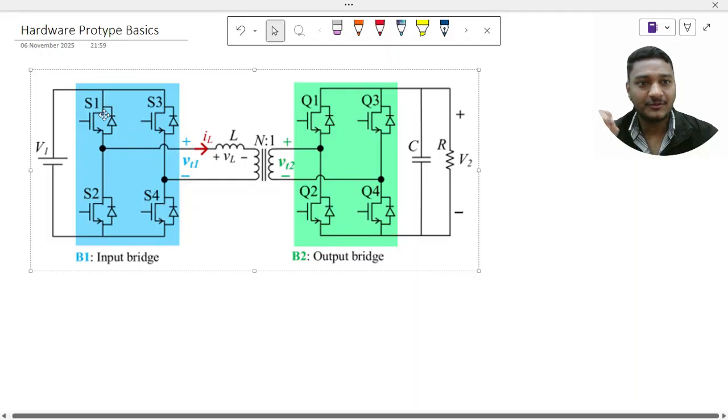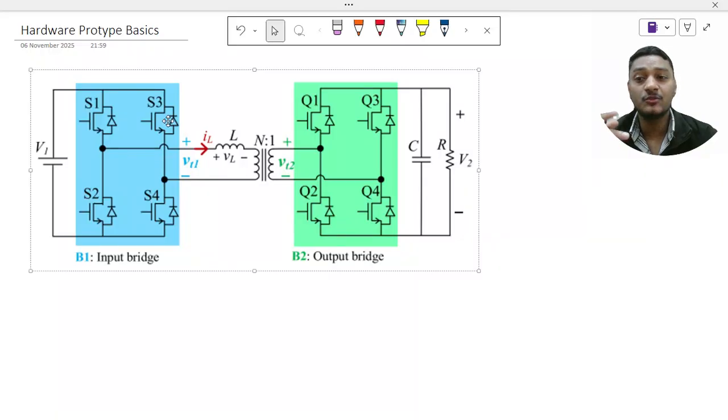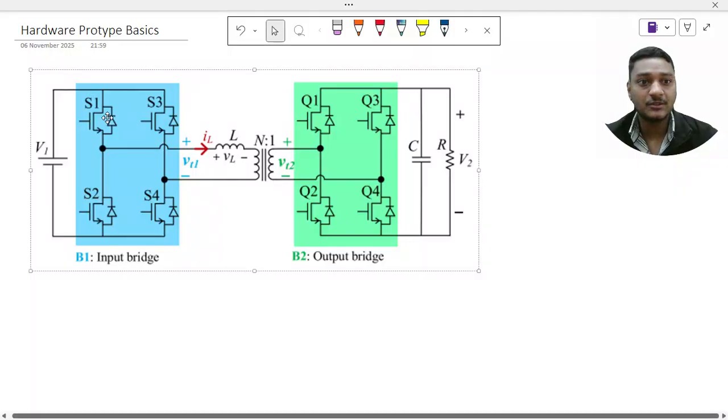What I am talking about is that selection of the MOSFET is a really interesting thing. It is not like if I want a 200 or 300 volt MOSFET, I can easily take any. You need to see a lot of parameters, like COSS, the output capacitance, the charge Q requirement, the RDS on, and how its RDS on is going to vary with temperature when I operate it in my environment.